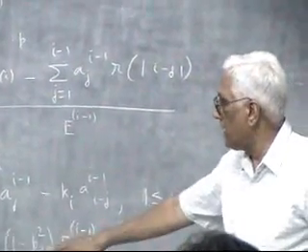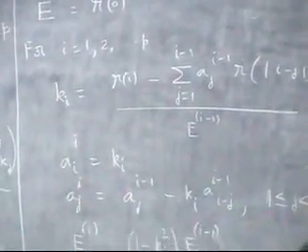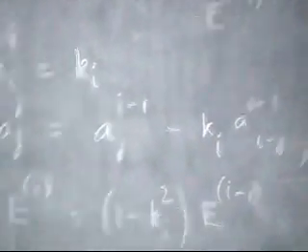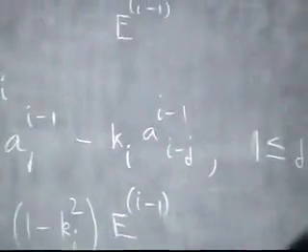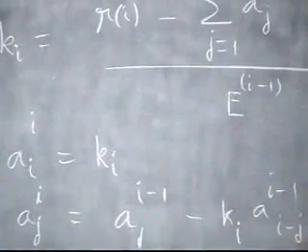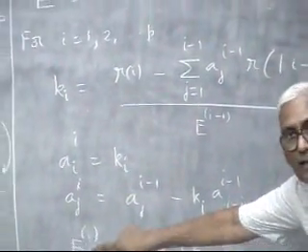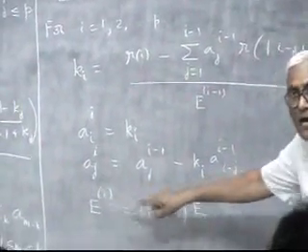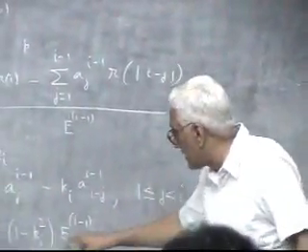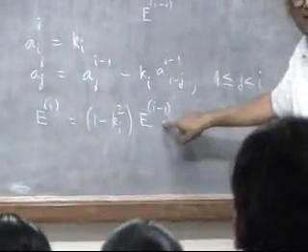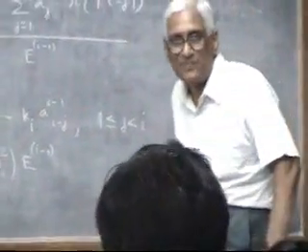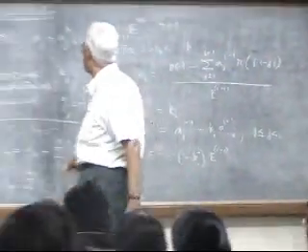What it basically says is, at every i, just as you have Ki, you also have Ei to pull out and have a look at. And that is true for that order also, i. So at the ith order, you will see this is what you get: the error, not energy, at the end of the ith order solution. And what it says is, the error at the i minus 1th iteration or order multiplied by 1 minus Ki square.